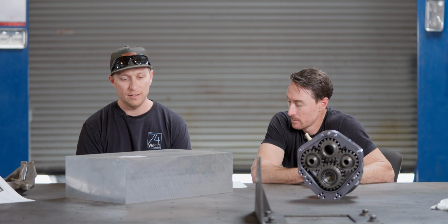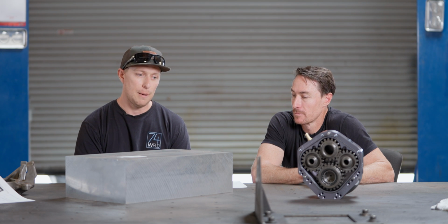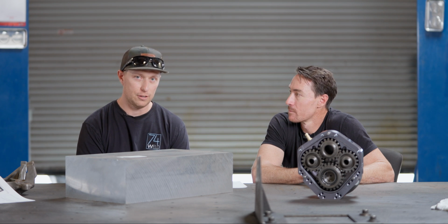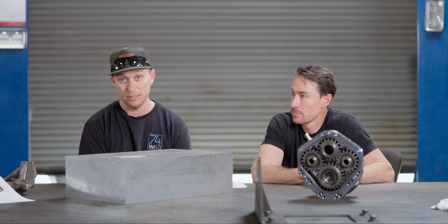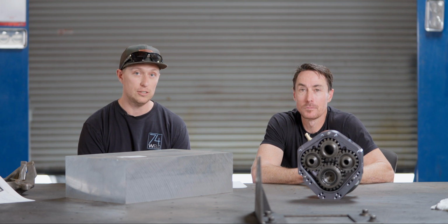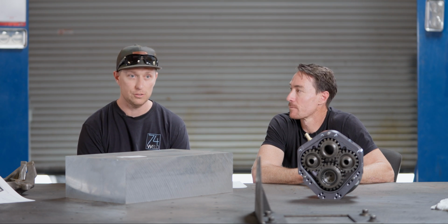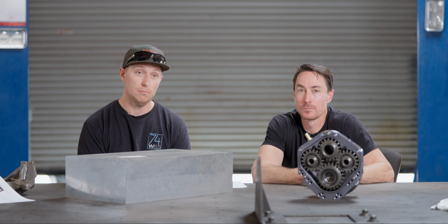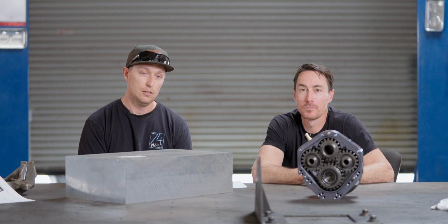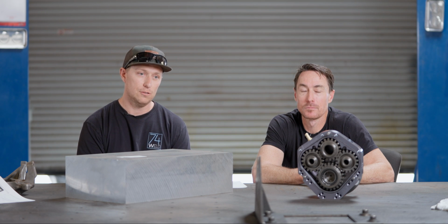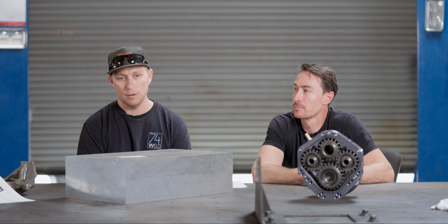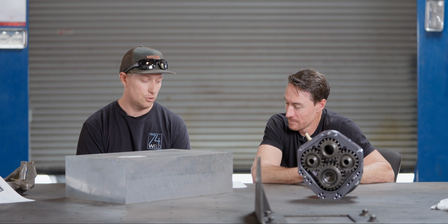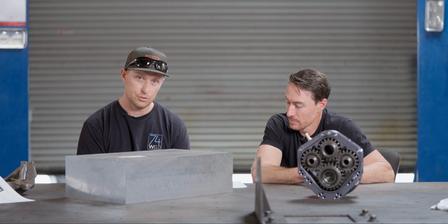When we're looking at a material, a good visual representation of a material's strength is going to be its stress-strain curve. So starting with stress, what is that? That's force over area. So same as pressure, that's going to be measured in pounds over square inch. If you have uniform force, the smaller area you have that force over, the higher the stress. Strain is going to be elongation of a material, deformation. We're going to measure that in percent elongation. And then two common strength markers that you're going to see are yield strength and ultimate strength.